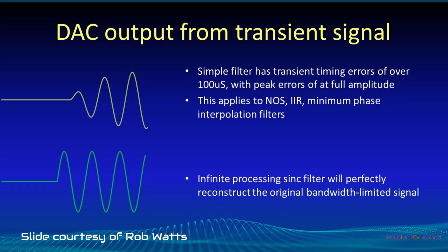What I realized was that if you didn't use a Sinc function, then your reconstruction of transient information would be severely hindered and altered. What would happen is that transients, when it goes to the interpolation filter, would either be slightly too early or slightly too late, and they will constantly modulate backwards and forwards. That modulation would depend upon the design of your filter, the music that's happening in the future, and the music that's happened in the past, because they all have an effect on your transient reconstruction.